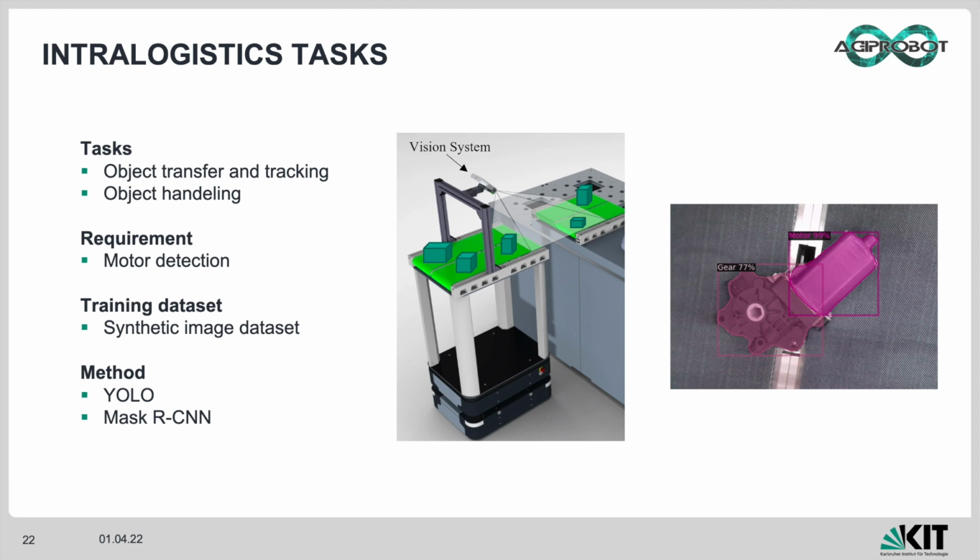Regarding the object handling task, the grasp detection system is the key entry point and includes the target object localization, the object pose estimation, and the grasp estimation. To solve the localization and the pose estimation problems for known objects, simple bounding boxes, as described in the previous use case, are not sophisticated enough. However, since the MotorFactory generates mesh models on part level, annotated instance segmentation masks can be generated. Training a segmentation network like Mask R-CNN allows detecting pixel-level segmentation instances of classes.